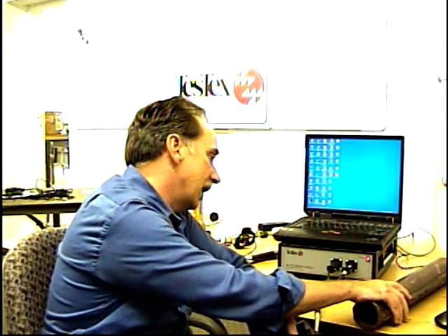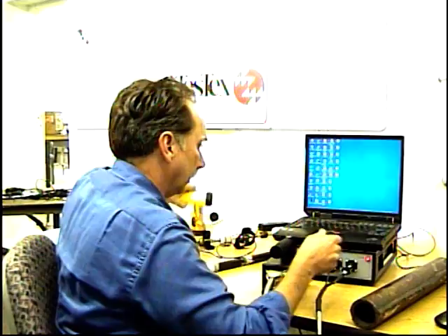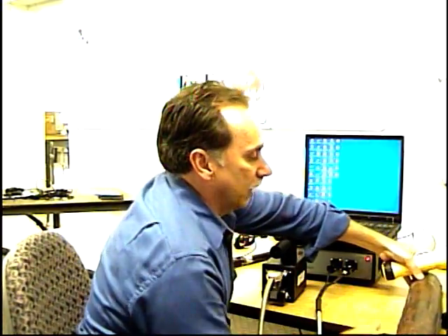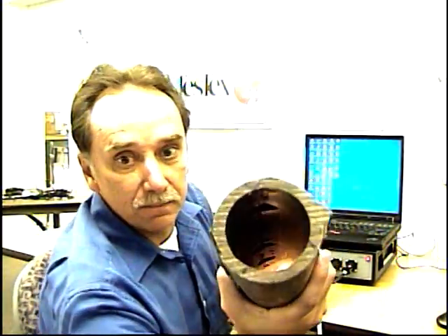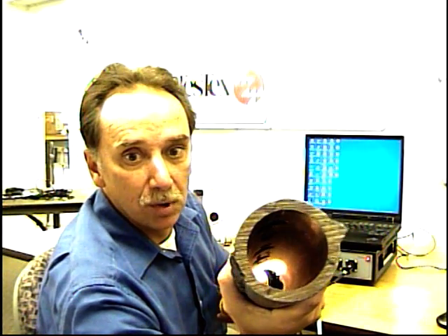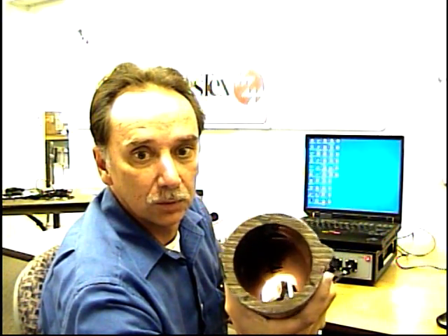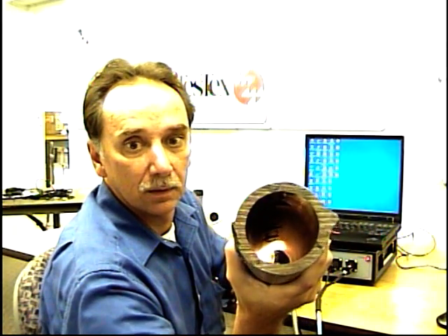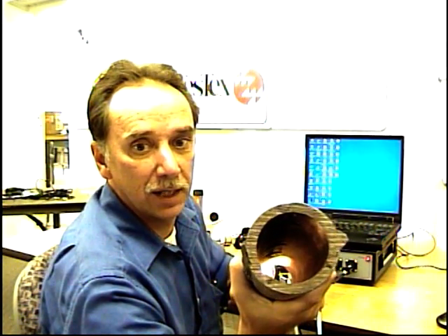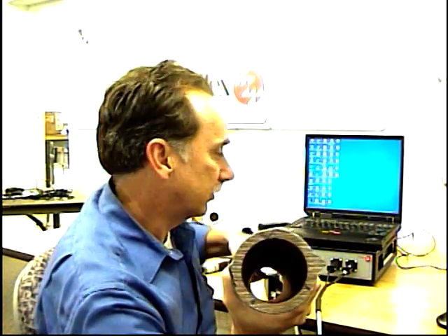We can put 6, 16, 32, or even 64 channels depending on how big the tube or pipe is. For this demonstration, we have a tube out of a water wall in a utility plant. Before I scan it, if you look inside, up at the top, I'll hold that right up to the camera. Like so, you're going to see there's all kinds of indications up top, and that's the area I'm going to scan for you.